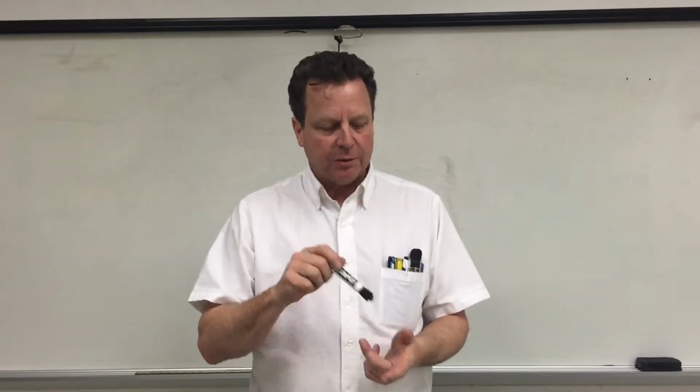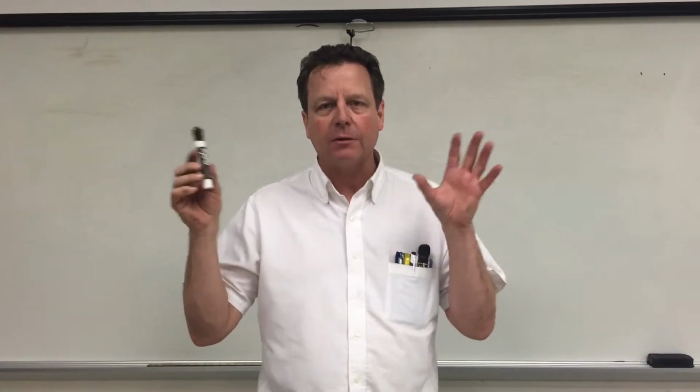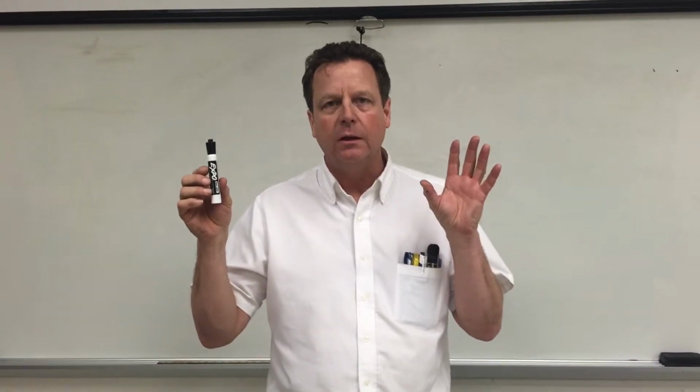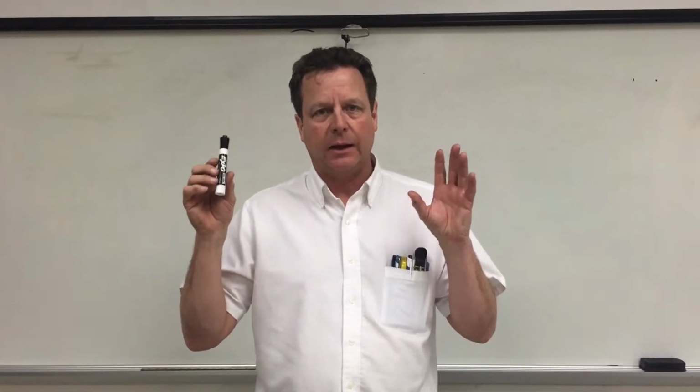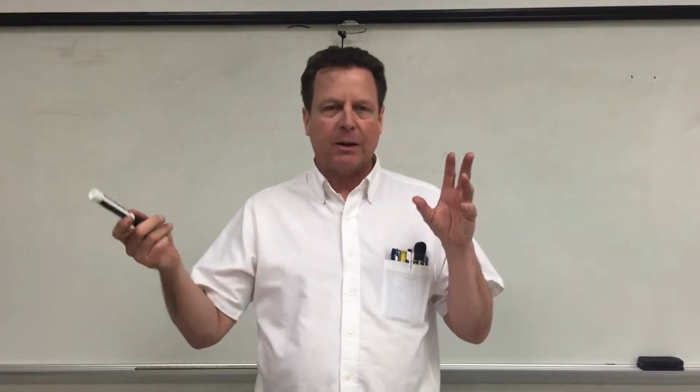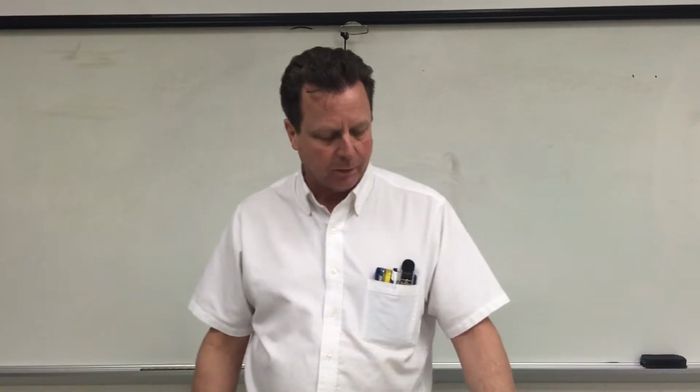And I want you to remember that you have to apply every tolerance to every dimension that you see in order to get the answer right, whether you have to divide it by 2 or whatever is going to be apparent on the print. But it's very important for us to be able to gauge these wall thicknesses and distances before we go out and make parts, so that we can keep our parts in tolerance and know their effect on the eventual end strength of the part.